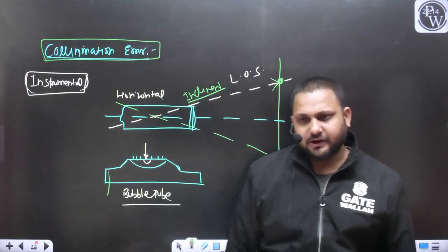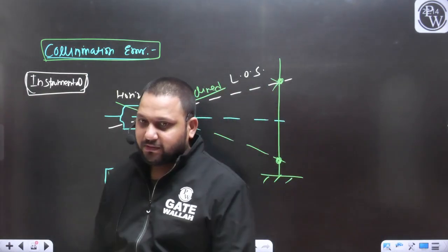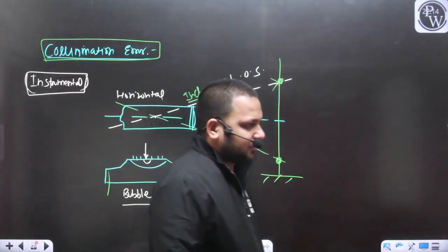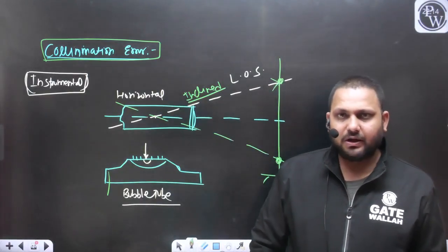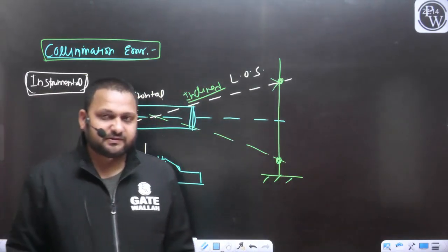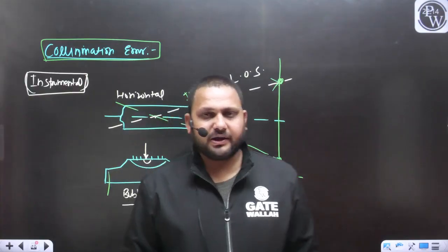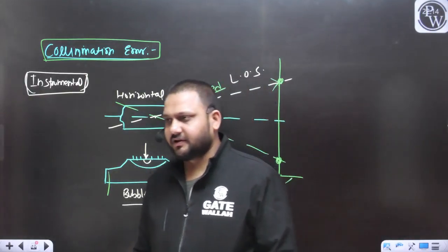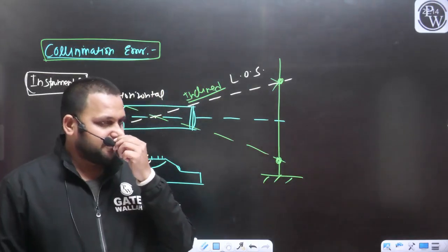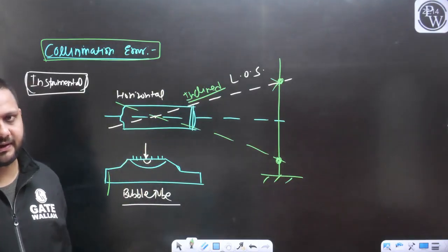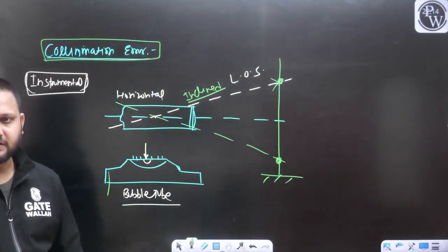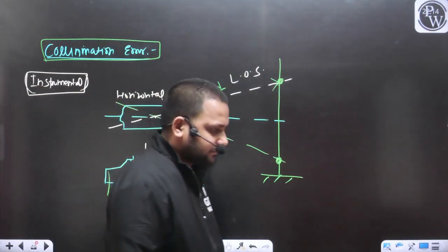In the theoretical questions they frequently ask, if we are going for the reciprocal leveling, what are the various advantages of the reciprocal leveling? So now I am summarizing. In the case of reciprocal leveling, there will be no correction required due to the curvature and the refraction. And with the help of the reciprocal leveling, we can also find out the collimation error. Here I have discussed what the collimation error was. Now I think the discussion is clear to everyone.